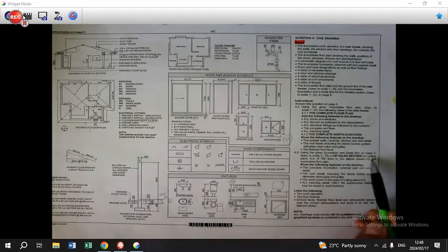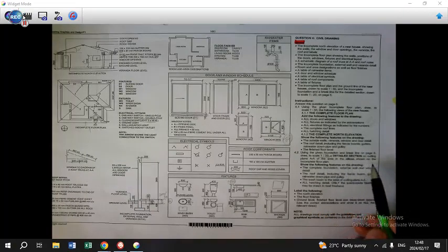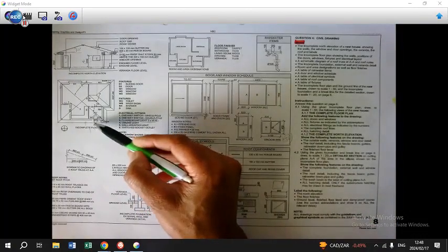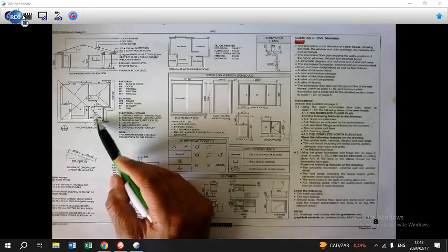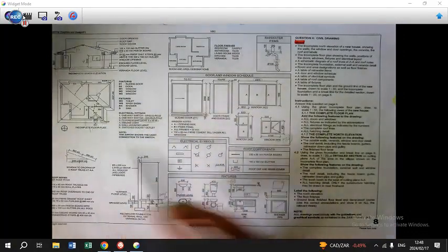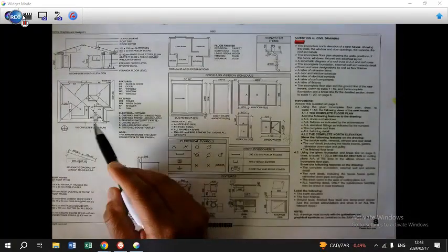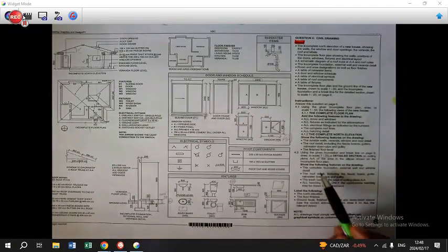Hence a detailed section on cutting plane AA of the area in the ellipse shown on the incomplete floor plan. And here you will see that that is the ellipse, and within the section of the ellipse you will have to cut through that and zoom in to a scale of 1:20. Keep in mind that it actually goes through window 3 as well.